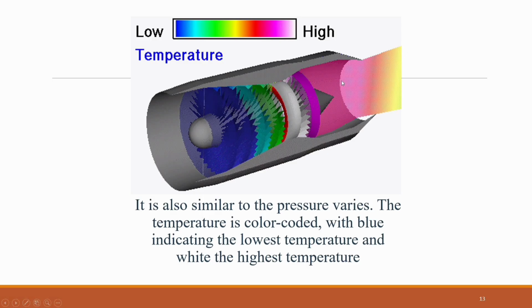Finally, the gases pass through the exhaust nozzle, where the remaining high pressure and temperature are converted into high velocity. The acceleration of the gases through the nozzle produces thrust, as described by the thrust equation. By observing the temperature variation throughout the engine, from low temperature at the inlet, rising through the compressor and burner, and decreasing across the turbine, we can better understand the energy transformations that make turbojet propulsion possible.